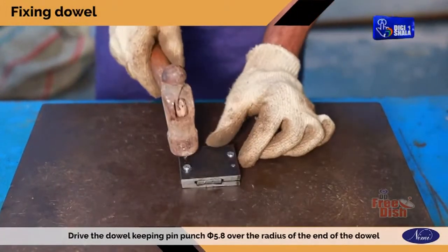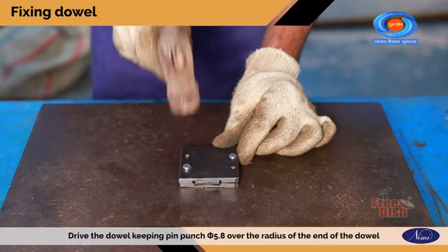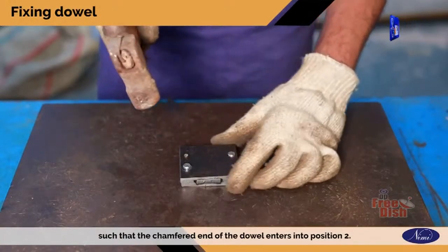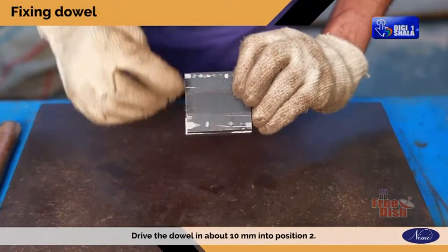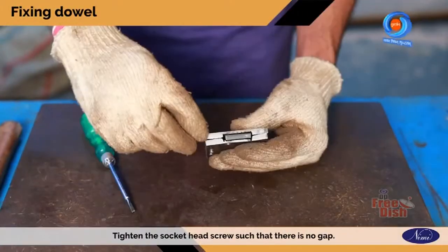Drive the dowel, keeping a pin punch of diameter 5.8 over the radius of the end of the dowel, such that the chamfered end of the dowel enters into position 2. Drive the dowel in about 10 mm into position 2. Tighten the socket head screw such that there is no gap.